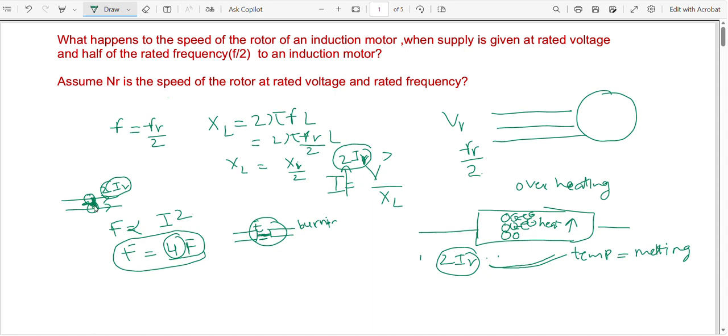When they get short circuited, due to the electric field, it will ionize the air gap between them, and a spark develops and it will completely burn off. So when the windings are getting burned, there is no magnetic flux, so the rotor speed will become 0.